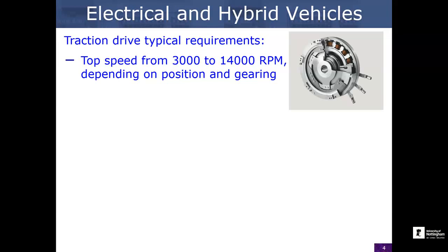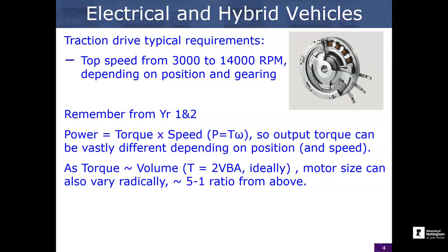One of the things you do find in automotive electrification is there isn't even a consensus on where you put the motors. We have people doing everything from putting the motors in the wheels, to putting the motors on either side of a gearbox, to putting them coupled to the combustion engine. But this changes the requirements quite a lot. If you have a motor in a wheel, it's got to go very, very fast, 14,000 RPM. It means you can make it smaller because of that link between rotational speed and power density, but it has other challenges. Or you might couple it directly to your combustion engine type drive shaft, and it'll be going at a few thousand RPM and then feeding a gearbox.